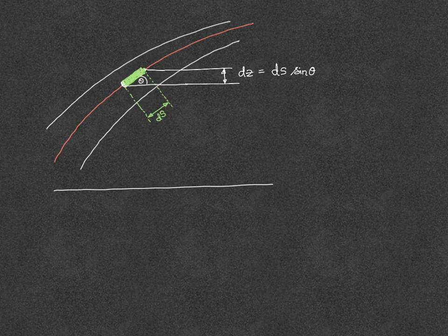Now we have chosen this very small cylinder. This small cylinder is having area dA, and the pressure at this end is P, and the pressure at that end is P plus dP. It varies along the streamline. So the force is P dA, and there P plus dP times dA. And what about the weight of the fluid particle?